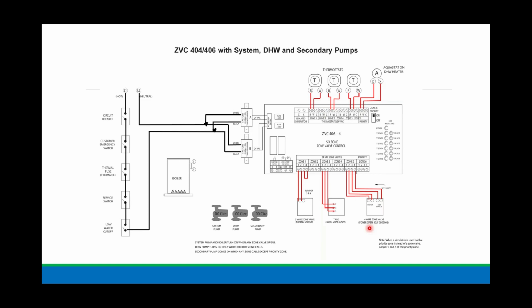That's the Tekmore Zone Sentry. We label on the valve motor itself 24 volts, so that's going to go to terminals 1 and 2, and the end switch would go to 3 and 4. You would use standard thermostat wire to wire that up. That valve does not come with wires, so standard thermostat wire.